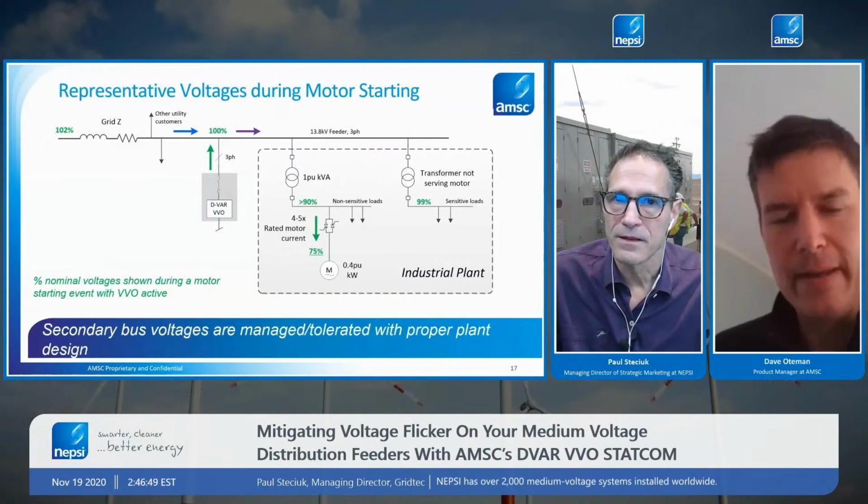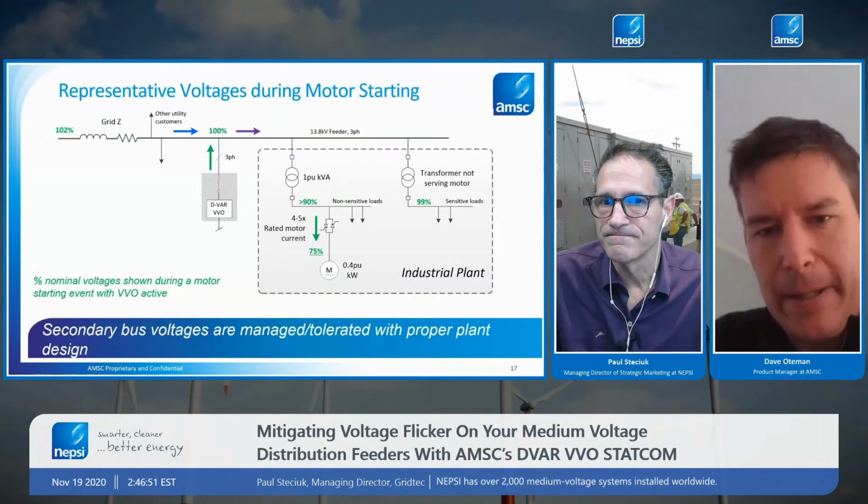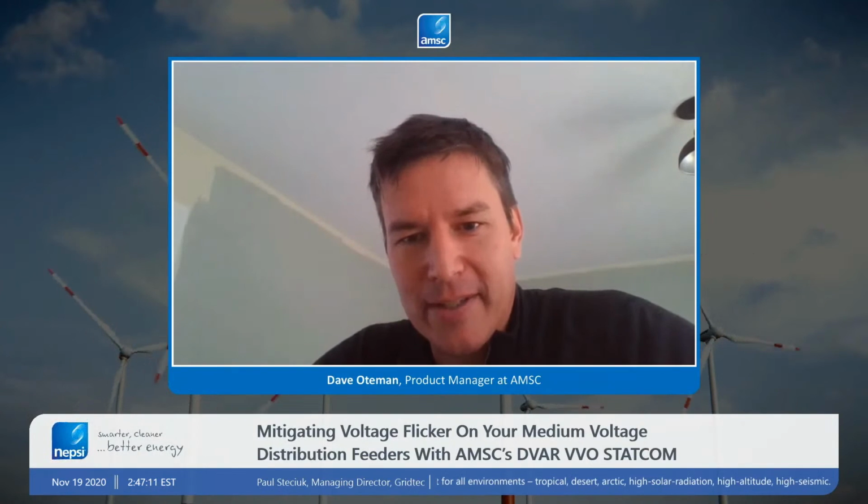Yeah, great. And I would say in our experience as well, we see that 90% range is typically not an issue at all. And the other thing is motor relays typically get set below 85% as well. So in that 80 to 85% range, you'll see undervoltage trips start to get set. So that's another practical consideration.